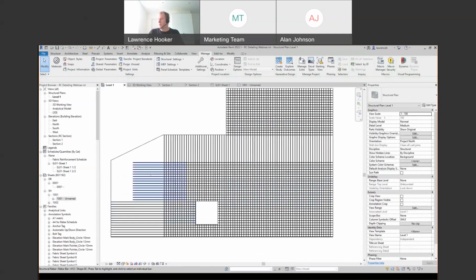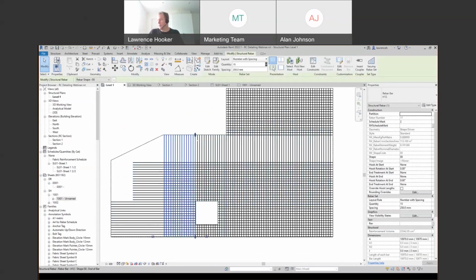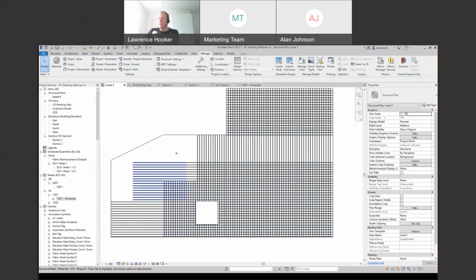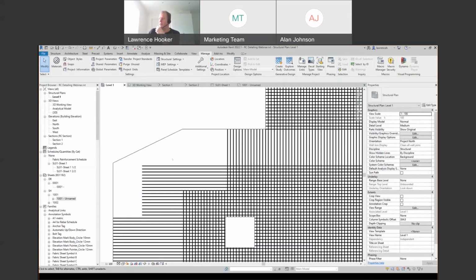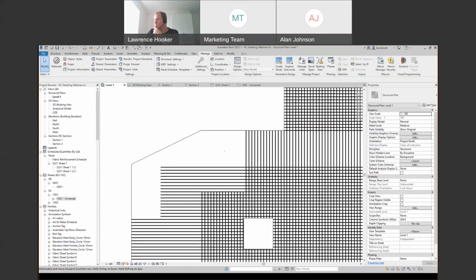Okay, good. So we've got some of that reinforcement bar in. You can see I've still got some adjustments to make for the stock lengths and so on. So we'll just change that to 6 in there. And again, I'll set that shape there to 0, 1. Right, let's now look at the varying range rebar that we need to place in over here.